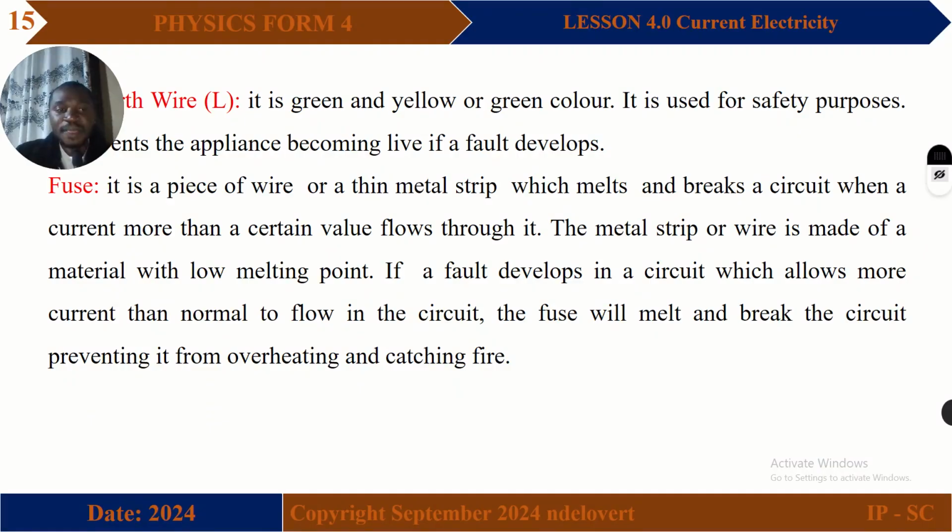So what's a fuse? A fuse is a piece of wire or a thin metal strip that melts and breaks a circuit when a current more than normal flows through it. The metal strip has a low melting point, and when a fault develops in the circuit and more current flows, the strip gets heated very fast and melts off. When it melts off, it breaks open the circuit, and current does not flow to the appliance anymore.